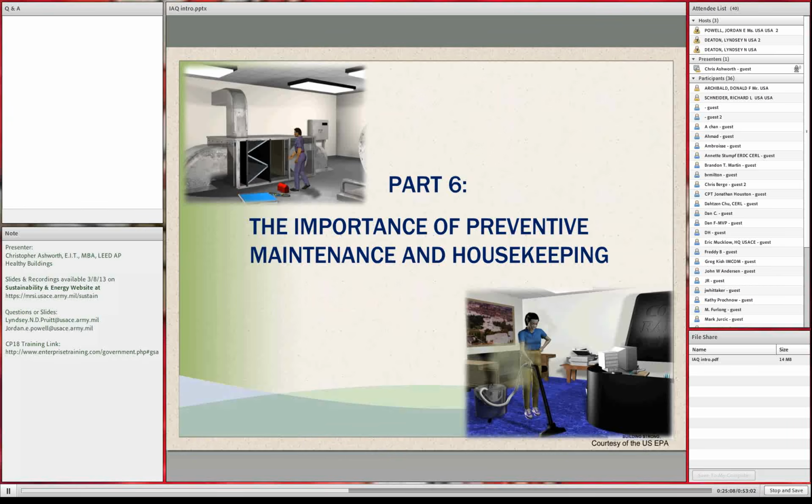The ducts were very clean. They were doing a great job, but they weren't actually creating a proper system. So you could just imagine if eventually this got clogged and there was this dust sitting around, people were having these various complaints. And I said, that's why I would recommend commissioning your systems and having somebody independent walk through your systems to make sure they're cleared after turnover.